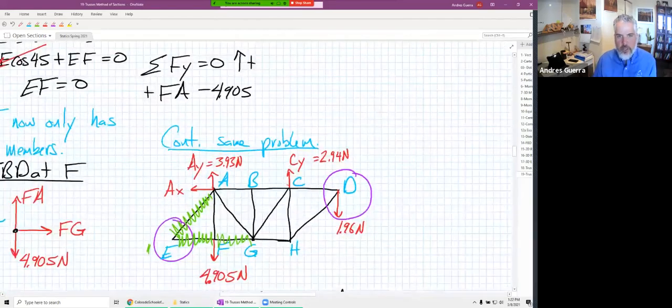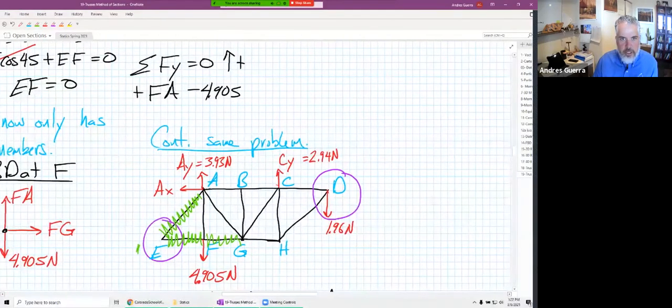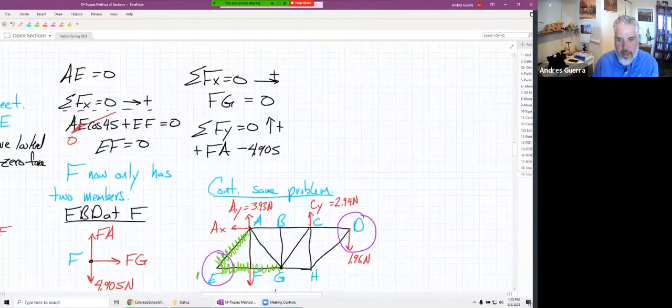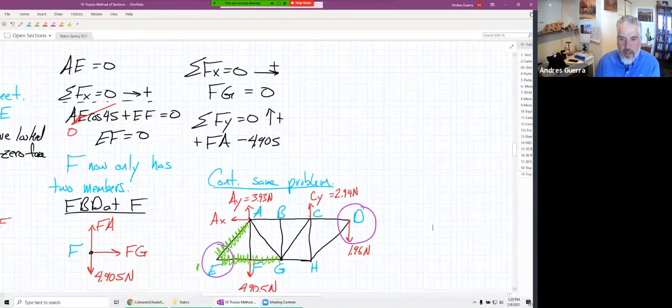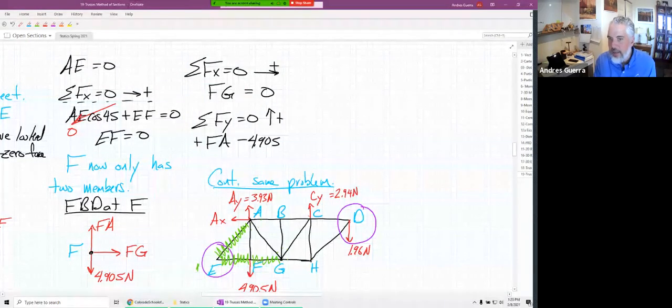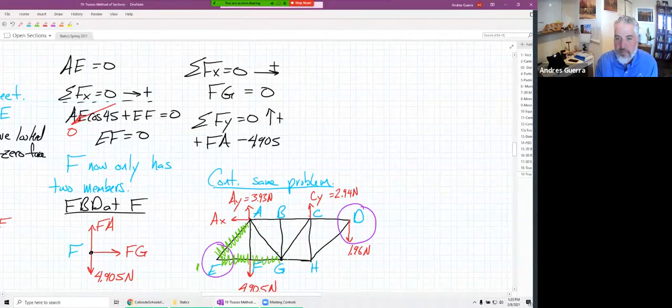And so we've destroyed those 3 members so far. But what about our other search criteria? I think we've exhausted 2 members meet, right? Well, we've already done D, so we're good there. A, how many does A have? A has 1, 2, 3, but we don't need to look at it. None of them are collinear. G has 1, 2, 3, 4, so too many. We don't need to look at it. H, there's only 3, but they're not collinear. We don't need to look at it. If they don't meet our search criteria, we don't have to look at them ever.